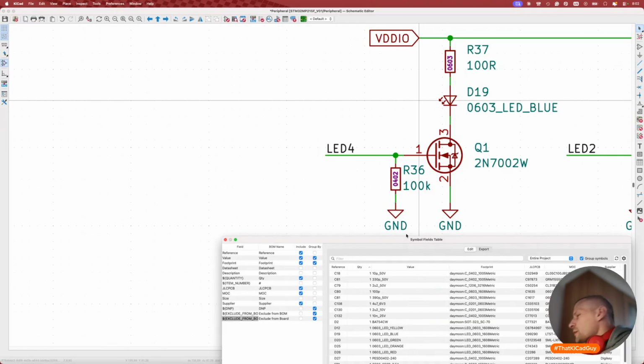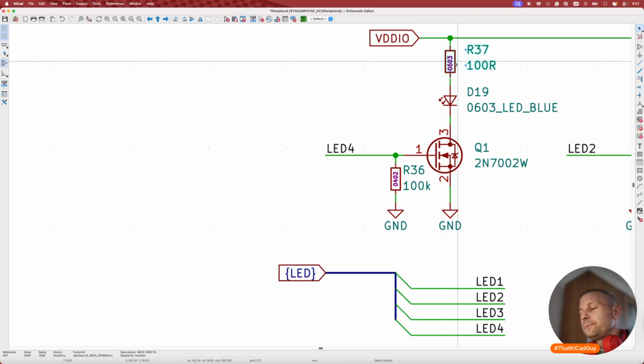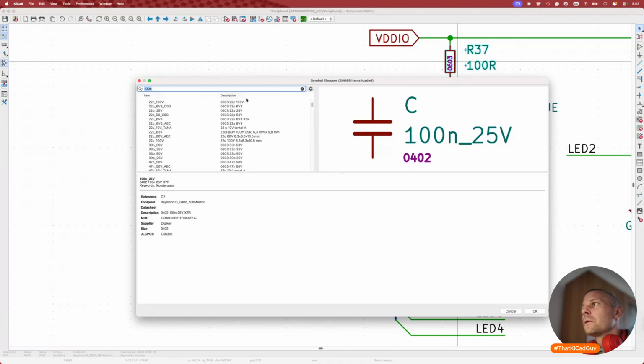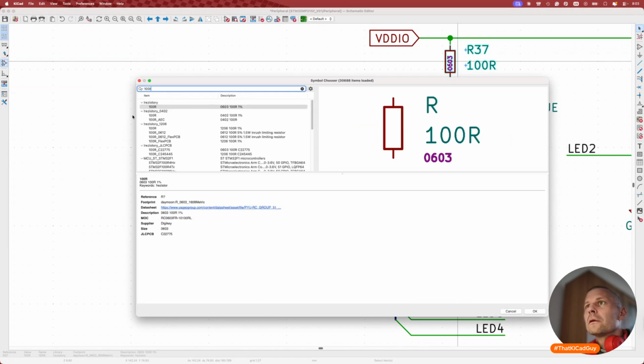What's the maximal dissipation power of this resistor? We have 3.3 V, we have blue LEDs, which is like 3 volt forward voltage. Let's say even if 1 volt is to be dissipated at the resistor, divided by 100 is, okay, it can easily be 0402. Yeah, this one.